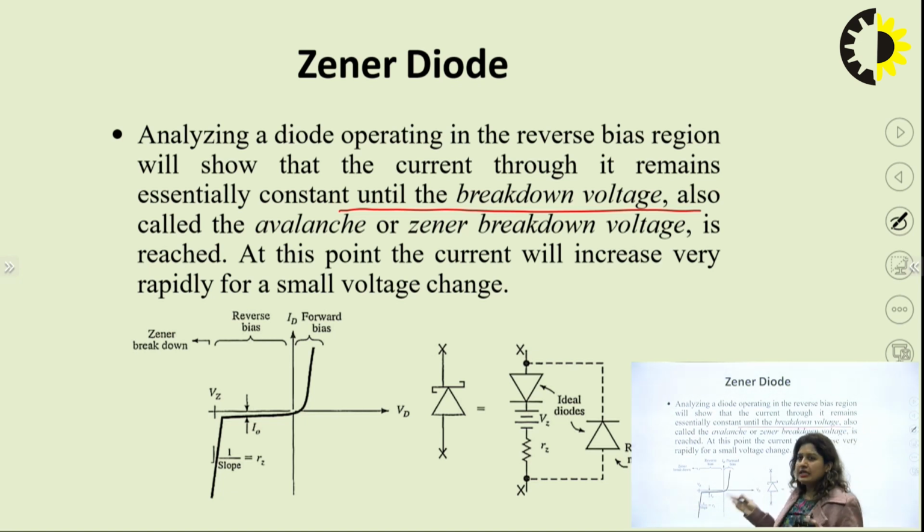The characteristic is almost the same. If you see the VI characteristic, when you increase the diode voltage there will be a change in the current in the forward bias. Similarly, when you increase the diode voltage in the reverse bias case, there will be a change in the current, but the current will drastically increase in the reverse bias after a breakdown point.